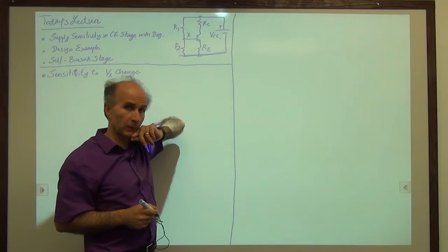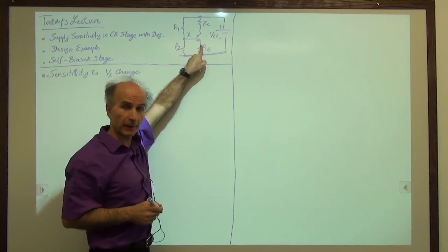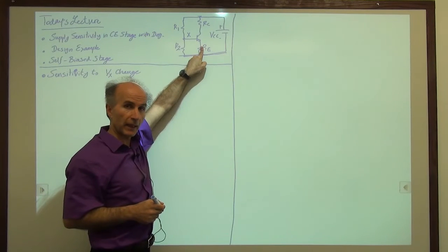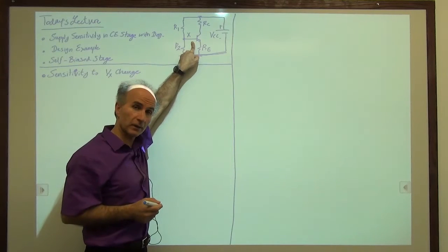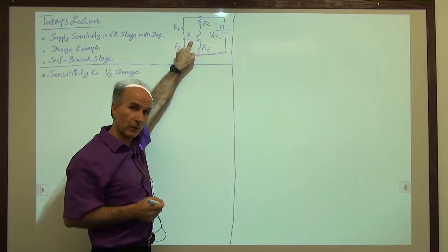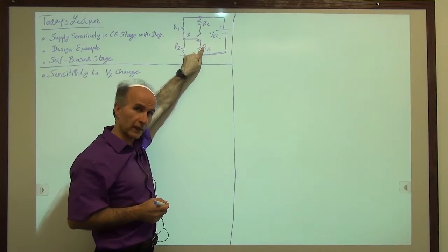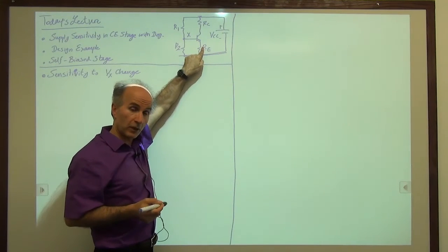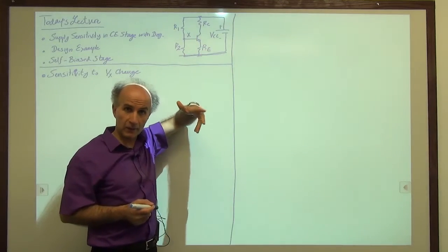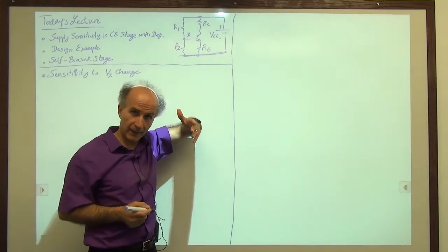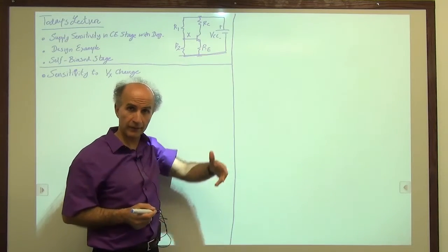All right, so what we will do first is we would like to see how much this voltage changes by. And let's assume that the change that comes here is not that large. If I have a small change at the base and I would like to find the change at the emitter, maybe I can just draw the small signal model of the circuit and analyze it, because the small signal model exactly represents a change in this voltage, a change in this voltage, etc.